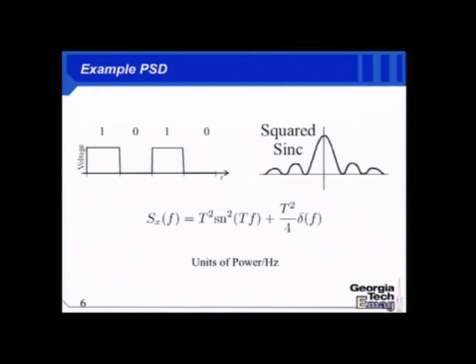The Fourier transform of a triangle is a sinc squared, which means the triangle's power spectrum is actually sinc to the 4th, which will ultimately tell me where the spectral energy in my power spectral densities is distributed. Sinc to the 4th dies out a lot faster than sinc squared. So triangles would clearly be a better way, if I could generate them, than a pulse.